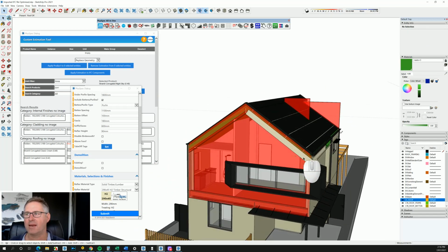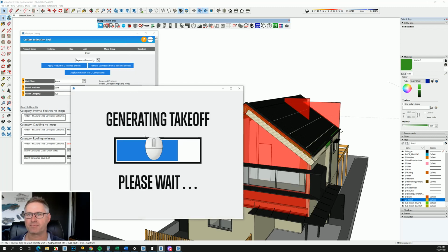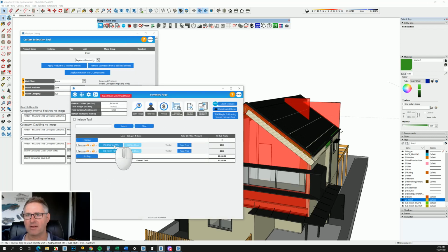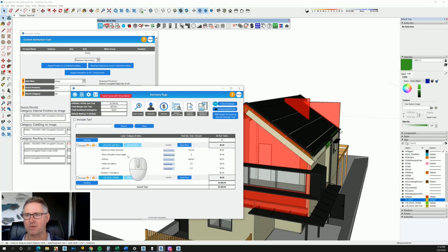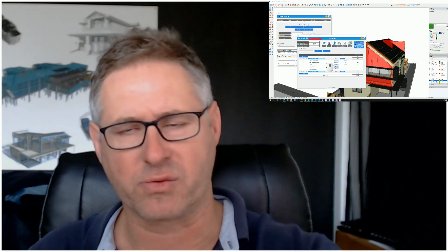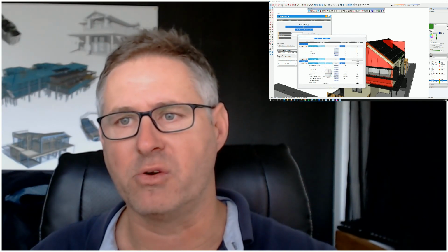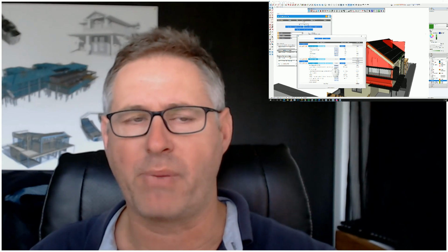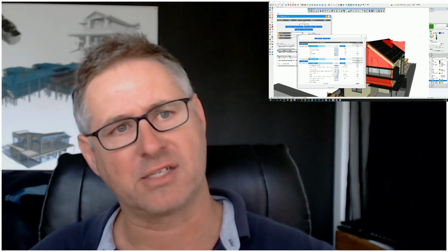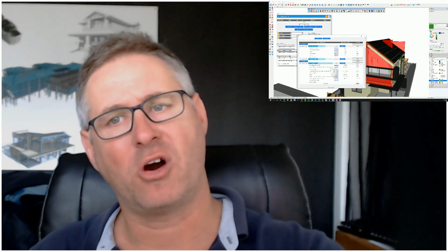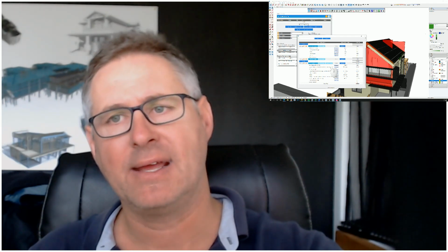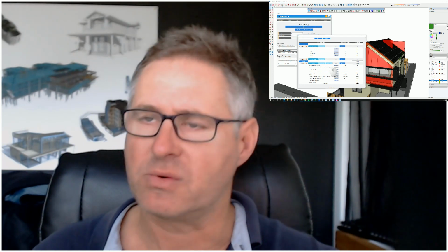All right. Now, obviously, when I do a takeoff of the model now, I'm also going to have framing in there. So now I have roof battens, and it tells me how many meters of battens I require, how many screws, because these are recipes associated with it. And guys, if you're not sure what a recipe is, it's basically when we say, okay, well, every square meter of roof or square foot of roof, you might have X amount of screws. So if I went to my roofing here, you'll notice that inside of my roofing, I also have screws to fix the roof to the batten, because it knows every time I need roof, I actually need screws. And you can assign as many different types of screws as you like, or as many screws per unit of measure, in this case square meters.